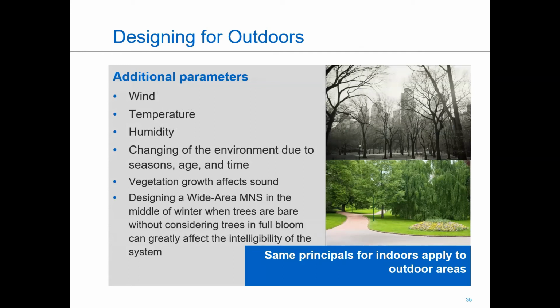Same situation. The parameters are very important. The same principles apply when we're talking about intelligibility. Now in reality, the products that we sell or manufacture have intelligibility specifications right on them, saying, hey, this product is going to be on the intelligibility scale at 100 dB at 100 feet. It's going to output with this particular speaker 123 dB at 100 feet and on the intelligibility scale of 0.8. So all this will be known in the cut sheets and the spec sheets.